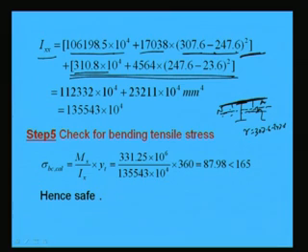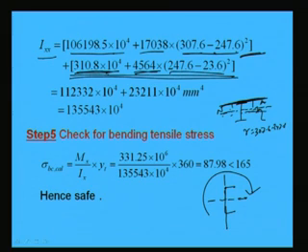So, 310.8 is the Iyy value of the channel section that has been taken, because Ixx is generally taken in this way, Iy is taken in this way. As it has been rotated, Iy will become Ixx and Ixx will become Iyy. So, Iyy plus area into r square means just shifting, because we know the CG distance of the channel section. Suppose the CG distance of the channel section is here. Because of shifting, total minus this will become r square, right.